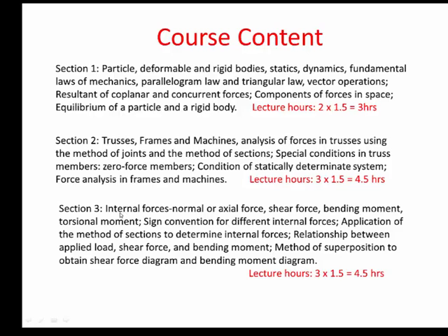Afterwards, we will go to find the internal forces, multi-force member and two-force member, where in the multi-force member you will have normal or axial force, shear force and bending moment as the internal forces. Before discussing how to compute all these internal forces, we will discuss the sign convention for the different internal forces, and then apply the method of section to determine internal forces in beams having transverse load, or basically a multi-force body. And then we will find the relationship between applied load, shear force and bending moment, and method of superposition to obtain shear force diagram and bending moment diagram.